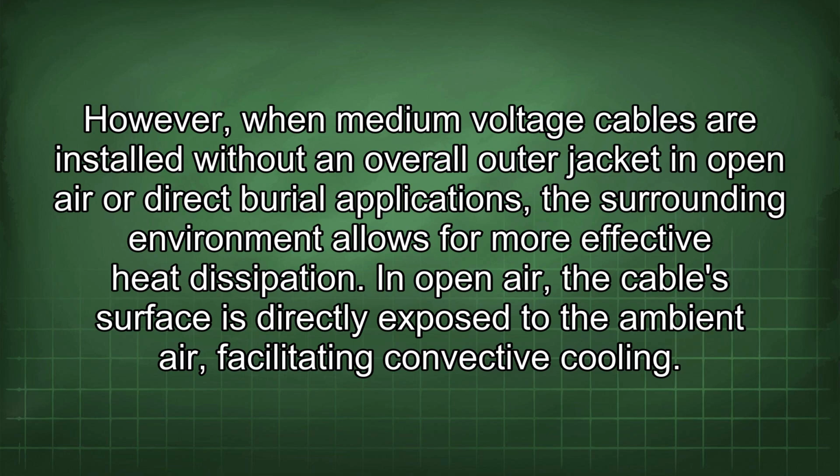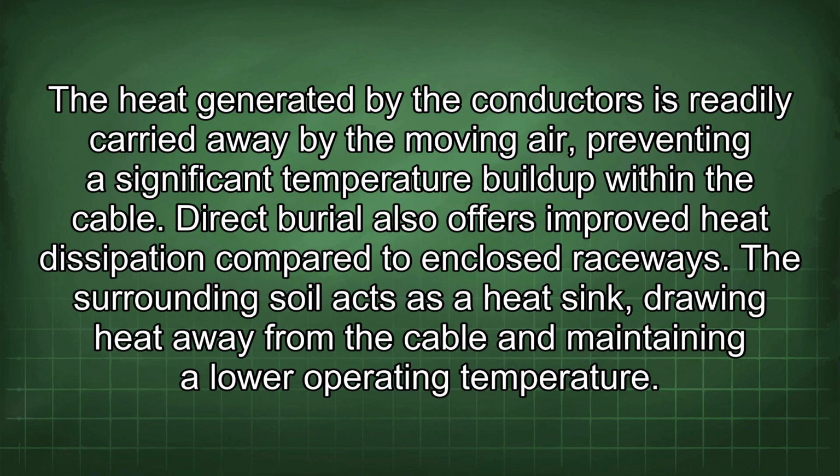In open air, the cable's surface is directly exposed to the ambient air, facilitating convective cooling. The heat generated by the conductors is readily carried away by the moving air, preventing a significant temperature buildup within the cable. Direct burial also offers improved heat dissipation compared to enclosed raceways. The surrounding soil acts as a heat sink, drawing heat away from the cable and maintaining a lower operating temperature.